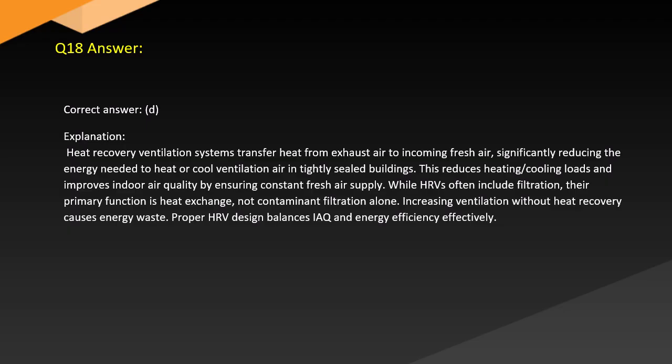Heat recovery ventilation systems transfer heat from exhaust air to incoming fresh air, significantly reducing the energy needed to heat or cool ventilation air in tightly sealed buildings. This reduces heating and cooling loads and improves indoor air quality by ensuring constant fresh air supply. HRVs often include filtration. Their primary function is heat exchange, not contaminant filtration alone. Ventilation without heat recovery causes energy waste. Proper HRV design balances IAQ and energy efficiency effectively.